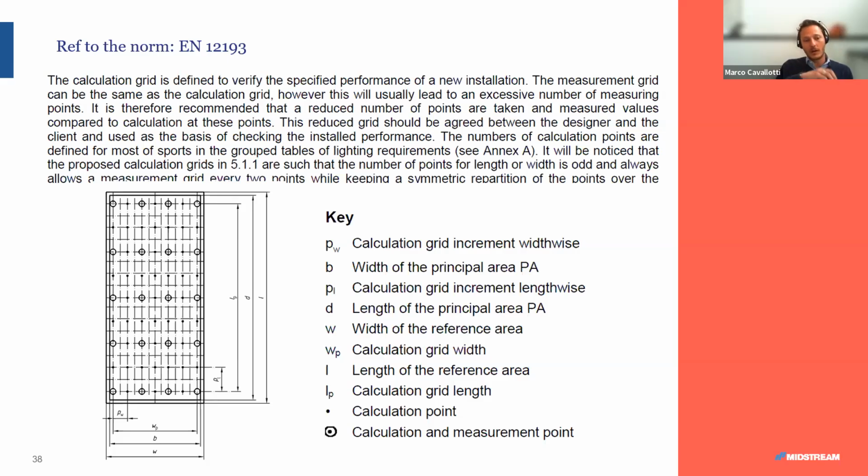So when we do the light checks on site for the aprons, for example, we just consider the amount of points and divide it by half, and then it gives you roughly 15 points for small aircraft stands and 25 for the big ones. So this is maybe because this is always a good question that the end user asked us when we do the commissioning on site.